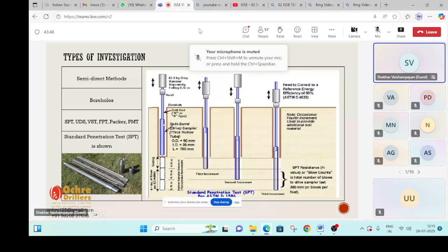right from the starting of maybe the 1850s, and this test has been used. And today, I'm using this word carefully, the shear strength of the clay soil is established or correlated very closely with the resistance that is measured, the SPT N value, or the blow count with this empirical method. The method is empirical. I'm repeating the word. This is not arbitrary. This is not experimental. This is an empirical method, used for correlating the shear strength of the soil with the number of blows. So it becomes a very important tool to us.